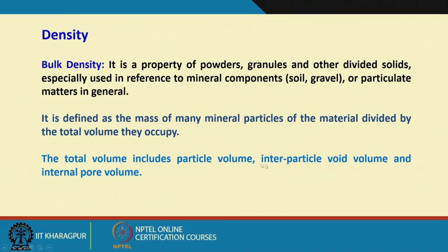The total volume includes particle volume, interparticle void volume and internal pore volume. That is, when I am pouring the bulk material into this, there will be some void spaces between the particles. That is again dictated by the particle size distribution and the shape distribution.